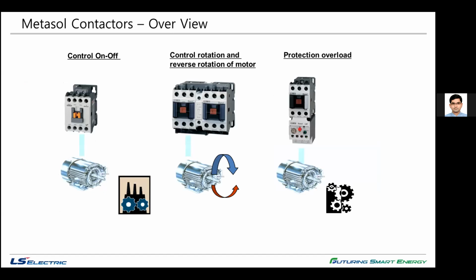Now, as Nirmal had already given you a brief on the application and where the MetaSOL contactors are used. Firstly, the main duty of the MetaSOL contactor is to control the on and off switching of the motors. Next, to control the rotation and reverse rotation of motor through reversing contactors. And the next one is the protection from the overload current.